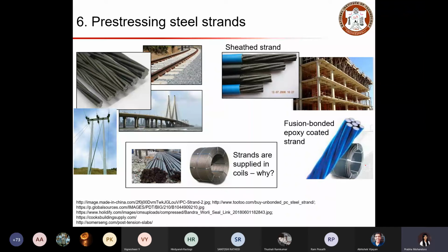In terms of yield strength or ultimate strength, however it is. So to compare with mild steel, that is 250, TMT rebars are 415 or 500 or 600. So what would be the range of this value for PS strands?